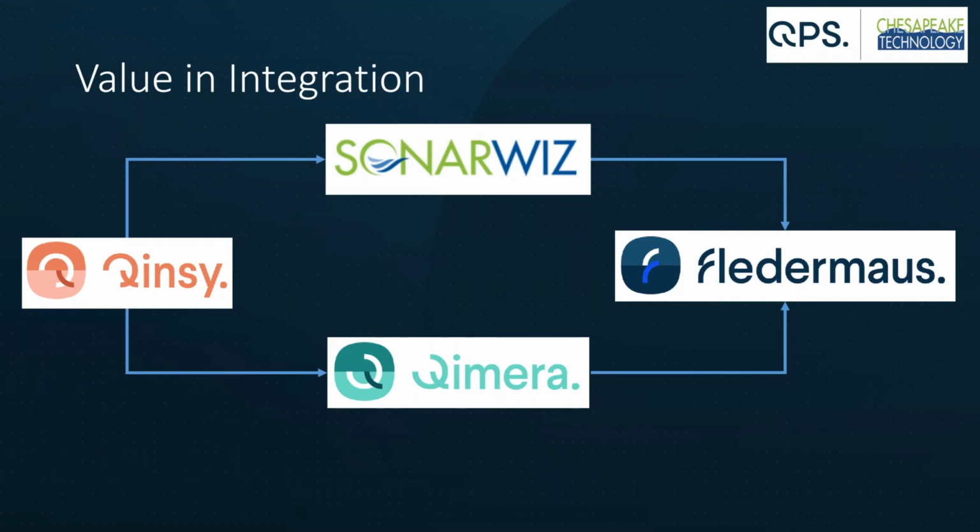We recently added a batch way of doing it. So, if you wanted to put a min-max filter for sound velocity, for instance, you bring in sound velocity and you don't want to look at each file. You bring them all in, say the minimum sound velocity is 1460, and then run through it all.